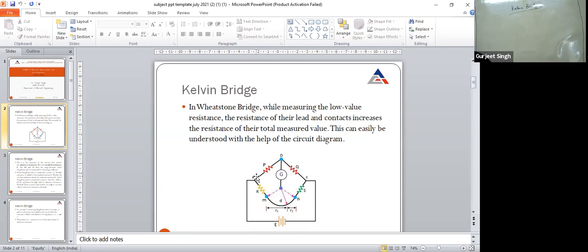We will not connect the galvanometer to the point M, because then the resistance of the wire from M to N is added to S, and when connecting it to the point N, the resistance of M to N is added to the resistance R. So we will not connect to M or to N. We will choose the intermediate point, that is the point D.